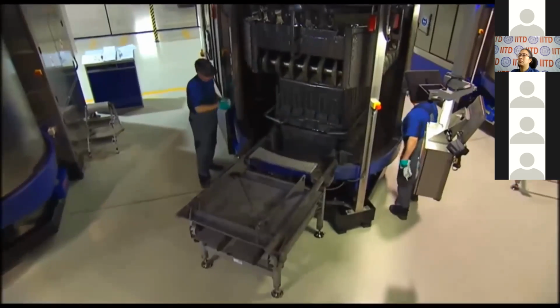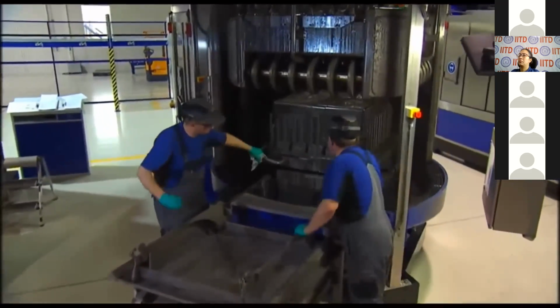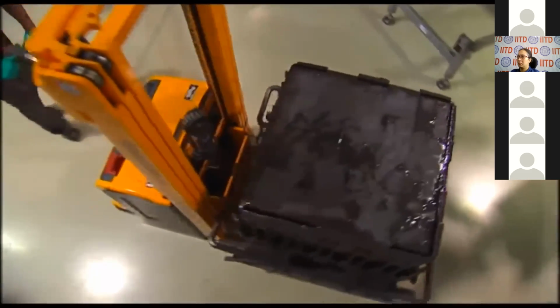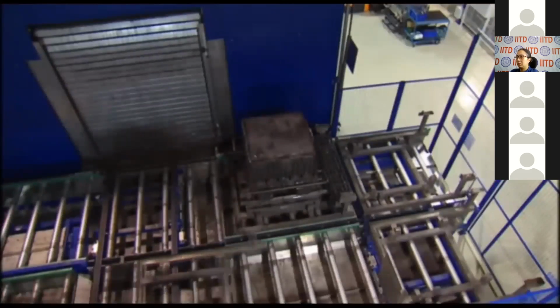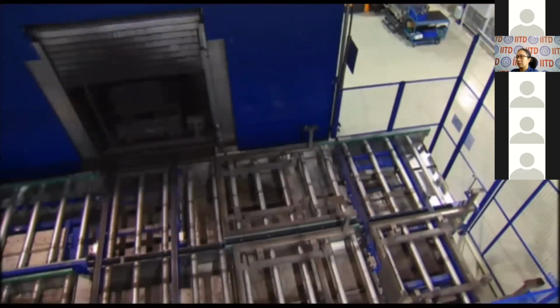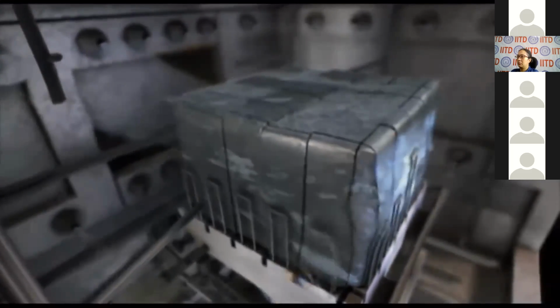The cutting process, during which the silicon ingot is cut into 25 bricks and side parts, so-called tops and tails, are removed, takes approximately 7 hours. Then it's time for a wash. Fully automated computer-controlled conveyor lines transport the cut ingot pieces to the ingot washing system. This latest generation cleaning system resembles an oversized dishwasher. First, high-pressure jets blow a cleaning fluid around the silicon ingot. A blower subsequently dries the bricks.